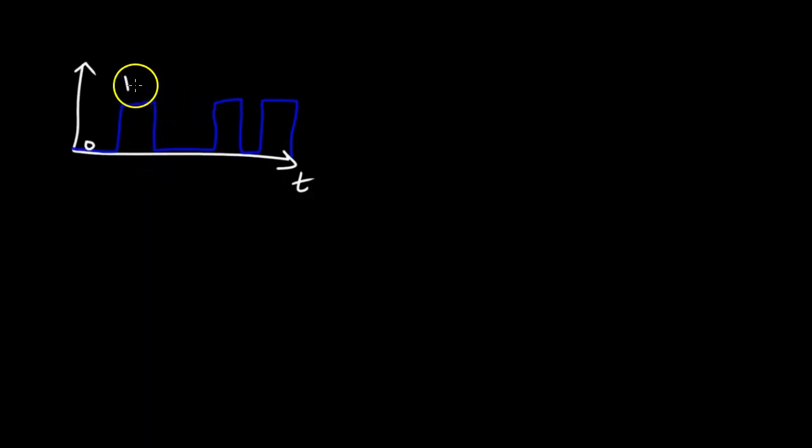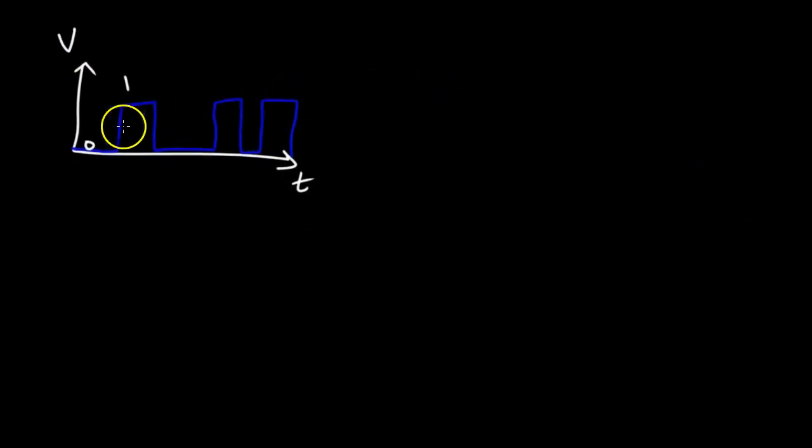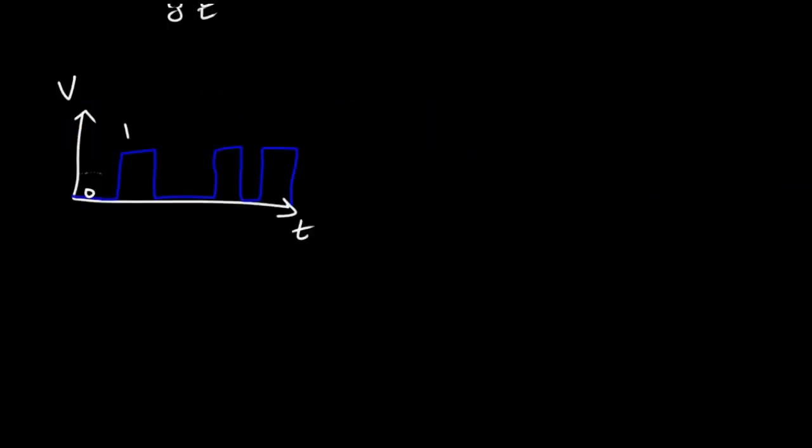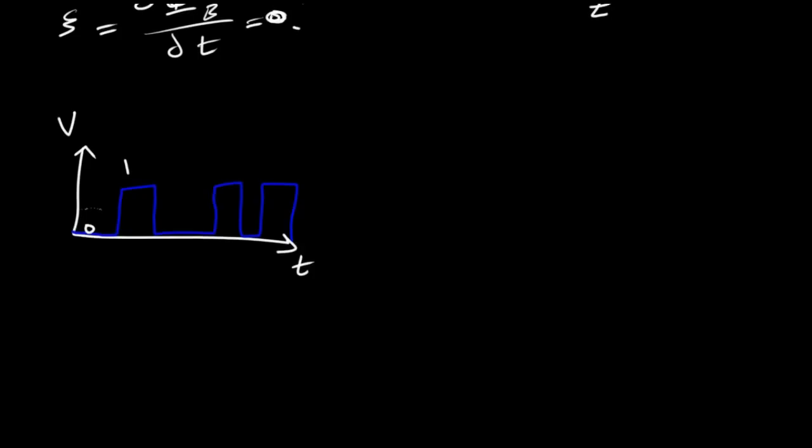So let's talk about the advantage now. Let's call this voltage again. What are the advantages? Well, what we can do is define a certain margin for this kind of system, for that same kind of device, instead of using an analog one as we showed up here, that has a very bad weakness of having jittery signals when electromagnetic interference is introduced to the system as input. What we can do is now use the digital system and define a certain threshold.